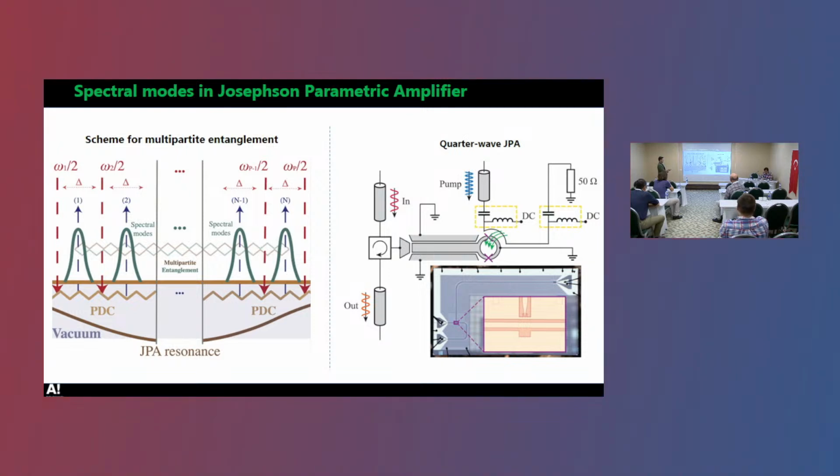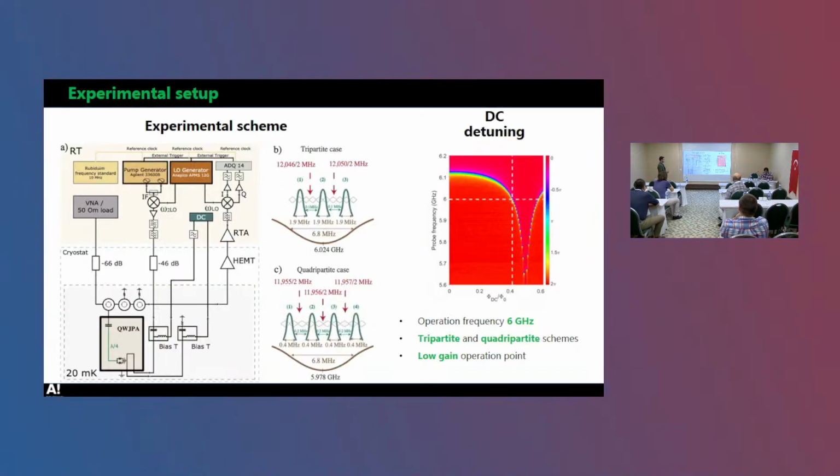And here you can see basically the circuit, so it's very, very simple. We just have a sample pad, then we have a resonator shunted by the SQUID loop. We guide our pump in here, so we apply multiple pump tones, and as an input we have just vacuum state, nothing goes into this system, but on the output we basically measure corresponding microwaves, and then perform the corresponding analysis. So that's a more extensive description of how this experiment is performed.